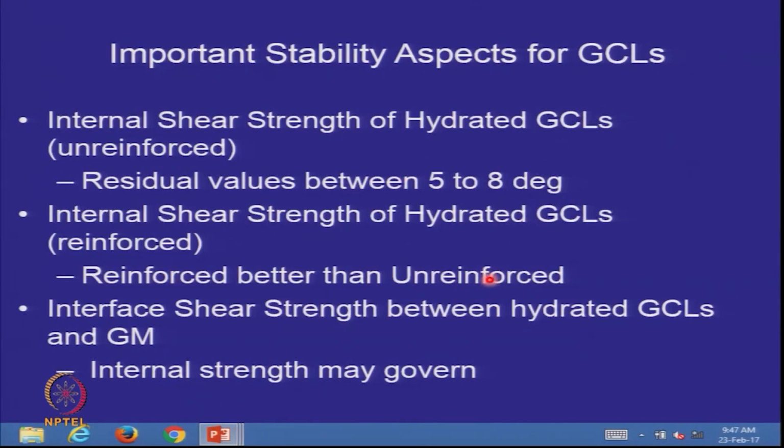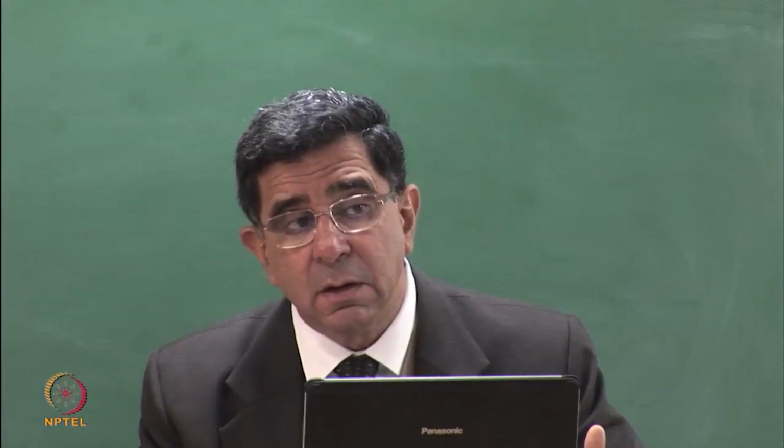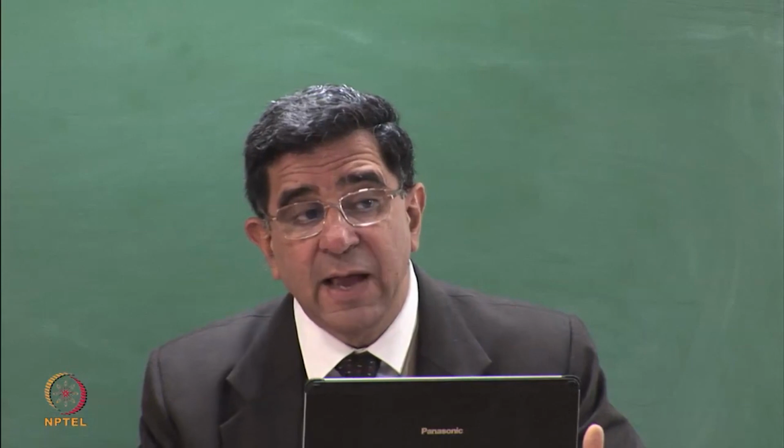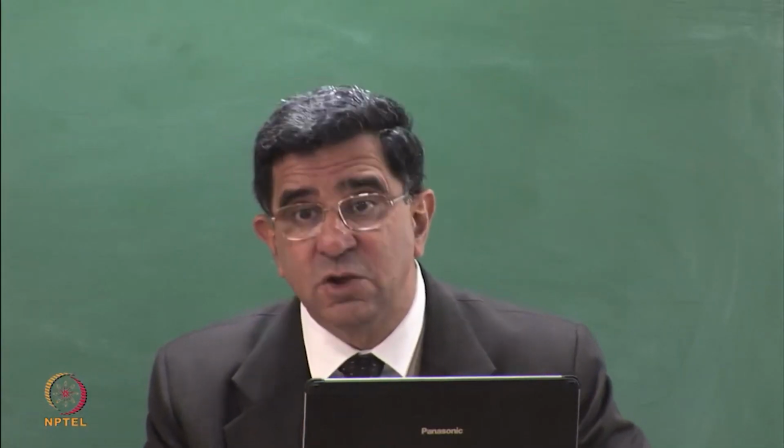They are more expensive, but all manufacturers will tell you that we have these two types of GCLs, and please be very sure that if you are using them on slopes, use the reinforced GCL.